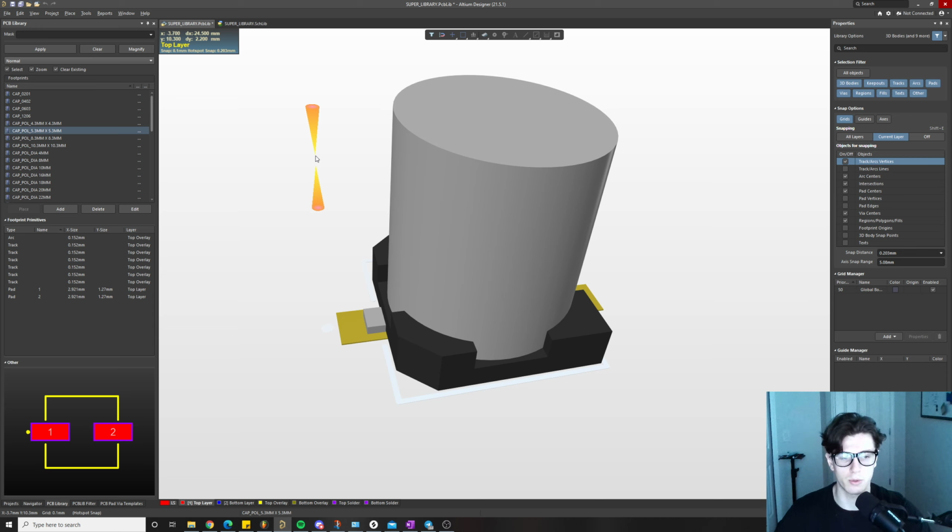So say, for example, you're trying to source a capacitor on DigiKey's website. You're most likely to find a capacitor that is one of these 4 footprint sizes, right? I mean, you can go a little bit bigger, but these 4 give you a huge selection. And so it just helps simplify your library. You only have a handful of footprints.